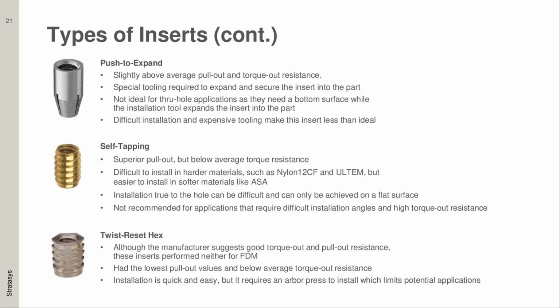Other inserts to consider, the last three, we have push to expand. So this does have slightly above average pullout and torque out resistance, but you do need special tooling, and it's not great for through-hole applications. So you need like a bottom surface to make sure it's aligned nice and square, and it can just be expensive and difficult to install. So we don't recommend those too much.